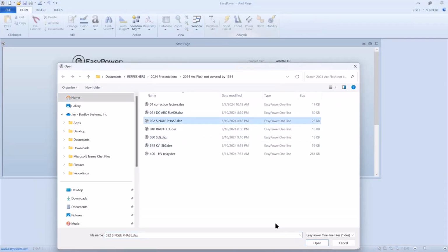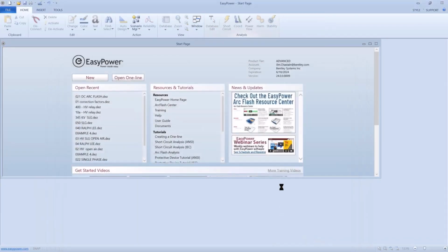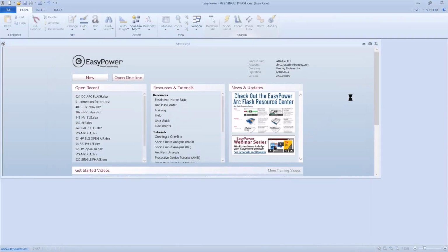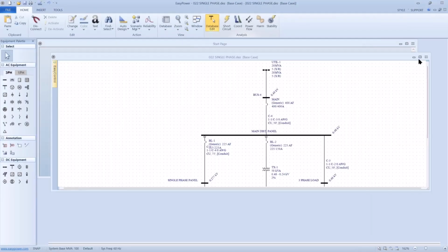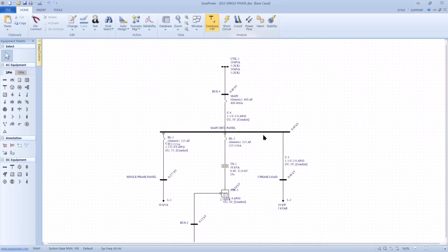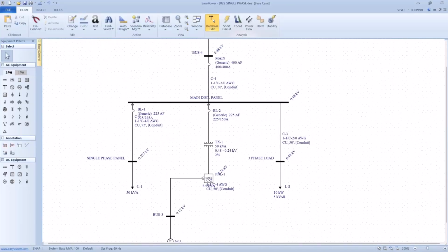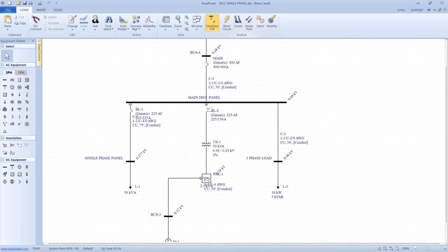So we're looking at single phase. And here we have both a three-phase and a single-phase system. For those of you that haven't done any single-phase modeling, this element here at the top of the feeder indicates that we've picked off B to C for my single-phase supply to this transformer. Likewise over here, this is supplied from A to N.